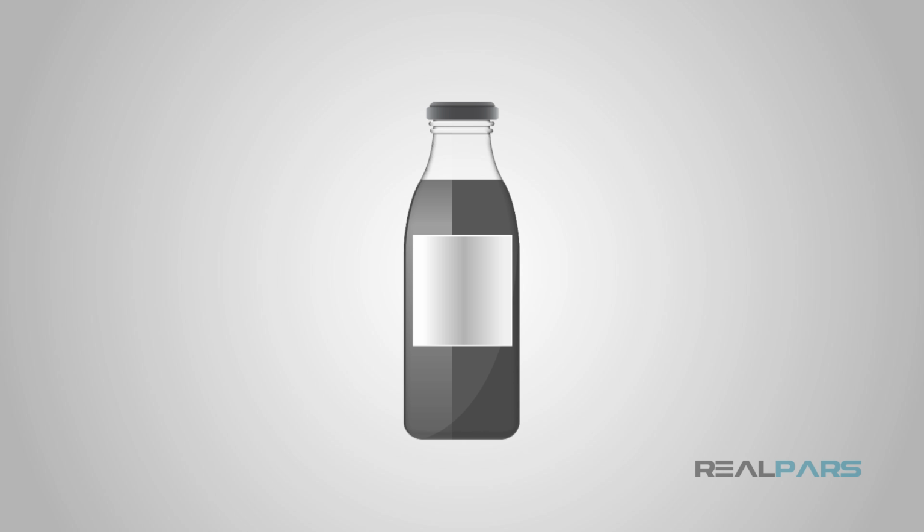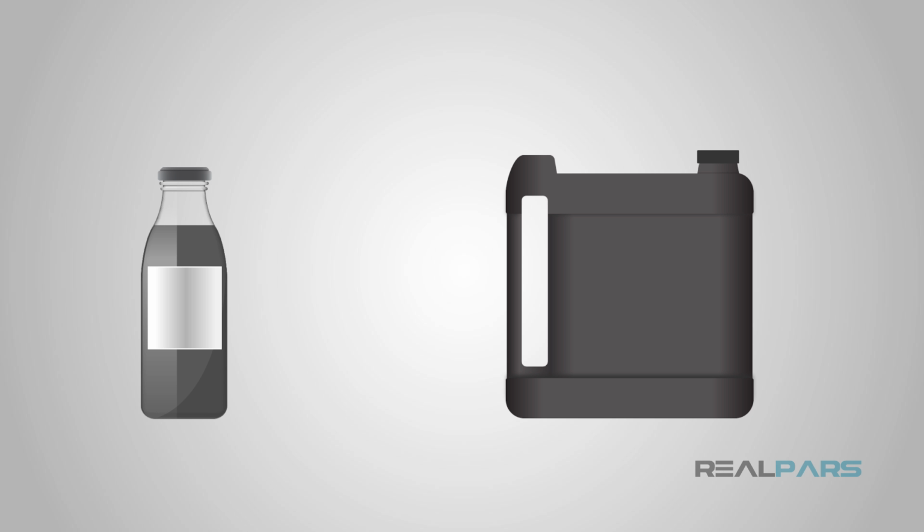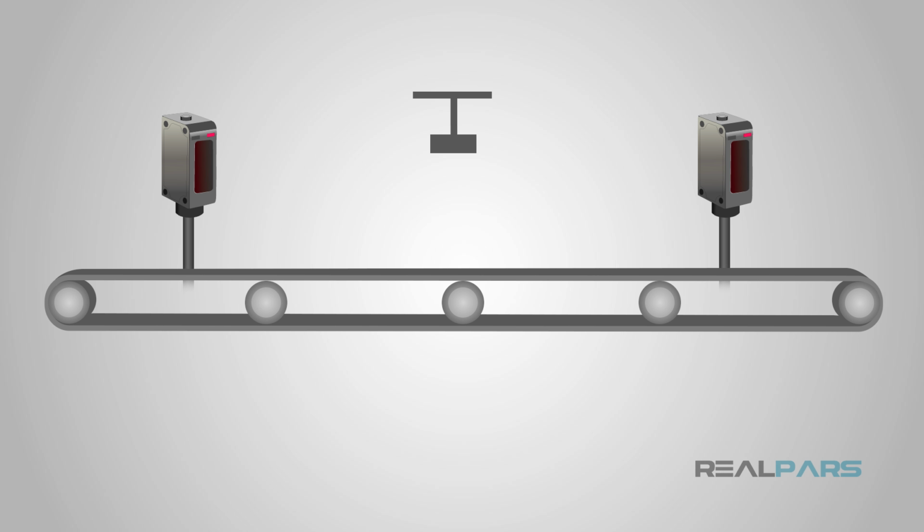Consider a prescription bottle. Easy, right? No handles, just a bottle that is a standard size. Now, consider an antifreeze bottle with a somewhat small cap and a very large handle. How in the world are you going to meet the requirements for the machine and remain flexible? If you put a pill bottle in, yep, easy peasy, right? Bottle in, seal, bottle out, no sensors blocked. If any of the requirements fail, bottle in, seal, tips over and isn't counted out, machine halts and alerts an operator of a malfunction.